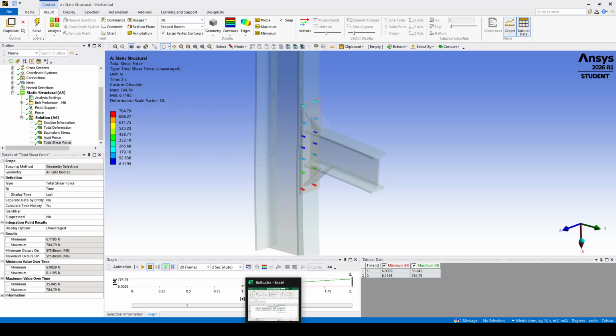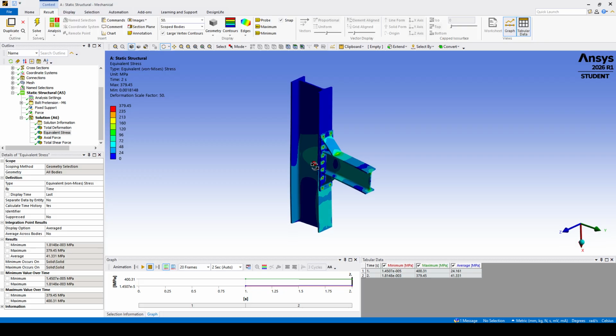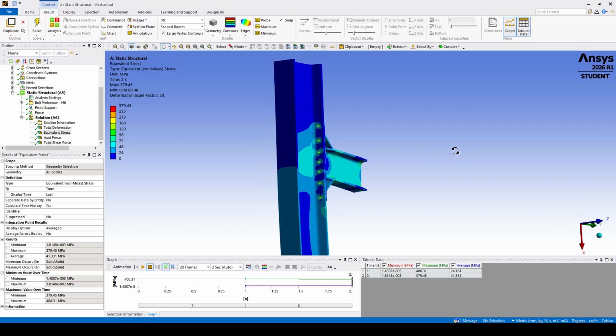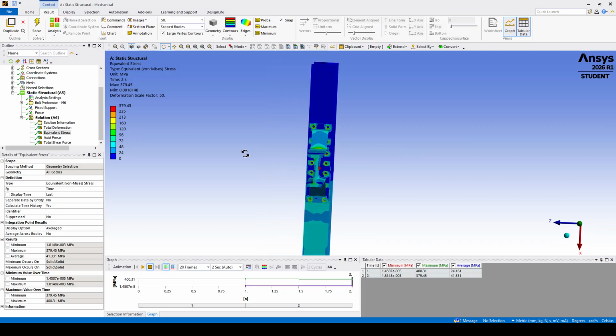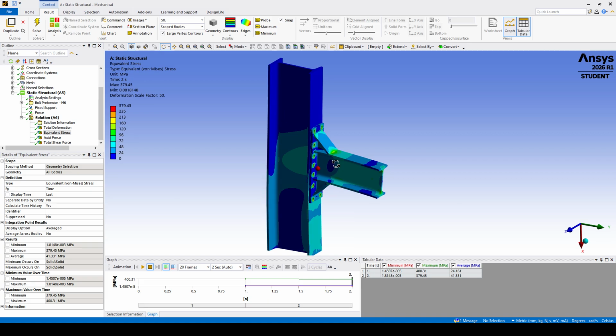In these videos, we learned how to simulate a bolted connection using ANSYS Workbench in detail, using the beam approach of modeling the bolts, and we evaluated the bolts. Under 10,000 newtons our structure seems okay. It seems there is no need for optimization, and we can investigate other things further.